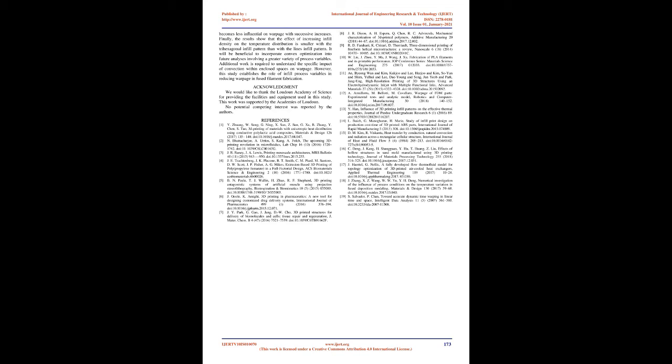Such a mathematical model based on the temperature distributions will provide ideal values for the process variables for different geometries. Future work may also include attempts to identify the role of natural convection on warpage, where the fluid motion of the air inside the infill transfers heat throughout the internal structure. As natural convection is a process that is difficult to quantify and study, this could be accomplished with thermal analysis and computational fluid dynamics simulation.